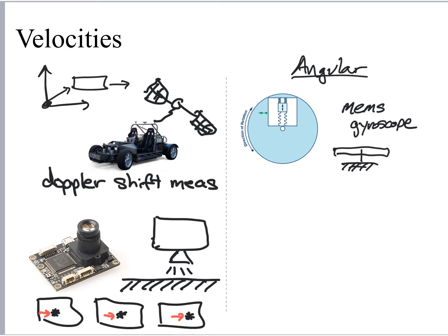And the reason that we do this is that if this is not rotating, the target mass just bounces back and forth in its original line. However, if we have a rotation in addition to this velocity, that's radial velocity, that produces a Coriolis acceleration. And the Coriolis acceleration is going to want to cause the mass to displace to either the left or the right.